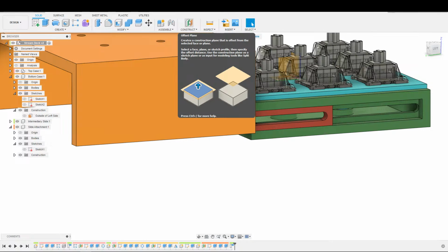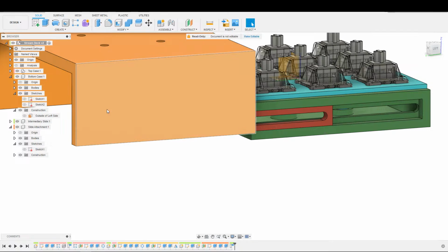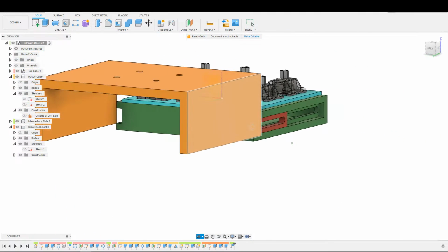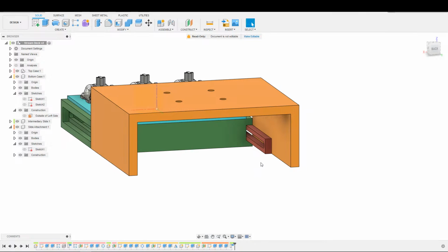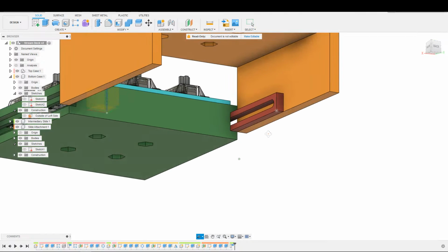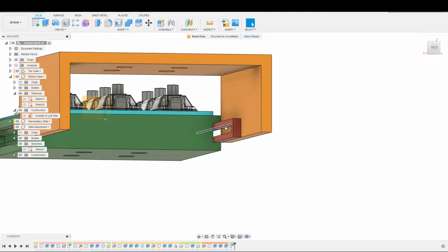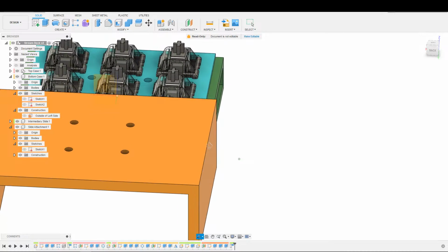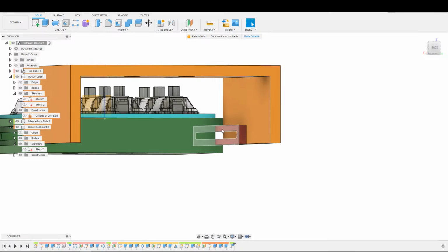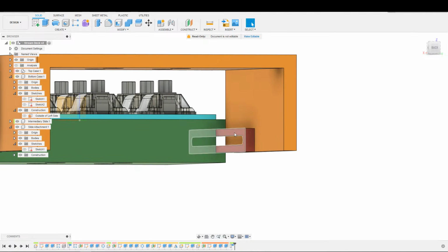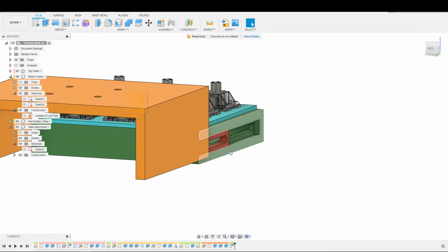So let's see. We're going to want to countersink. Now, which way do we want the bolt to go? I think we want the bolt to go on the inside. And if we want the bolt head to be on the outside, the bolt stem to be on the inside is what I meant to say. So that means we don't necessarily need to capture the bolt on this guy. I mean, we kind of do, just to make sure it doesn't go anywhere. It's just a bit difficult because it's only 2mm, right? Is all we gave ourselves. So we only have it partially captured, which may be alright. So let's just get moving and see what happens, I guess.